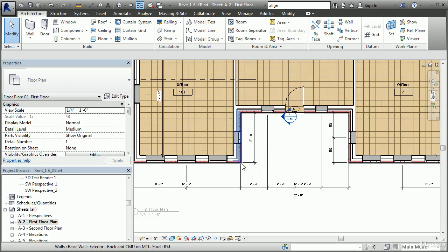Now it's really kind of fun to add all of these constraints and these alignments and locks. You do need to be careful and not put too many in. Just because you can doesn't mean that you necessarily should lock everything down or create too many constraints and alignments. When you add too many constraints and alignments, the model size will get too large, and sometimes you'll get unintended consequences. The relationships and the locks and constraints can propagate and compound across the project, so that you can change the location of a wall on one side of the building and a window on the far side of the building might move as well.